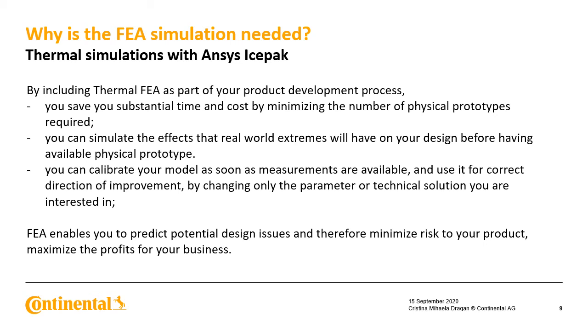So you can calibrate your model based on thermal chamber conditions and use it for car environment conditions. Another advantage is that, compared with measurements, you can for sure change only one parameter and really count on the direction of improvement. During measurements, there is also environment noise, which in general influences the results quite a lot.